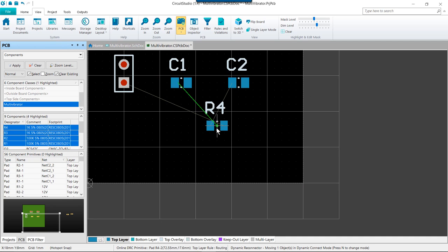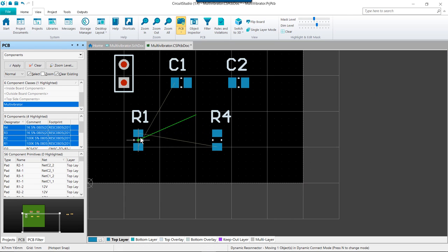So let's go ahead and place all 4 resistors near the bottom of the PCB. Finish the rough positioning of your components using the image here, or just follow along with what I'm doing. Remember, the space bar will rotate in increments of 90 degrees anti-clockwise as you drag them, and so we can see the connection lines are shown. And then let's go ahead and get these parts in position. Don't worry about the positioning being exact. We'll go ahead and use a quick alignment later.